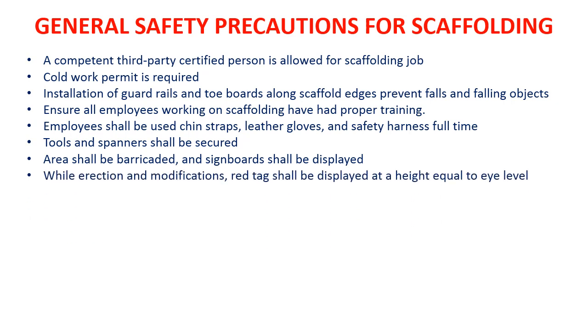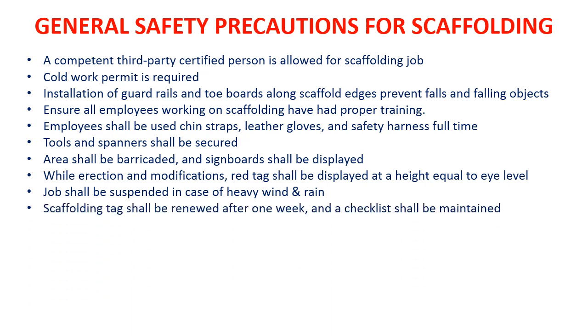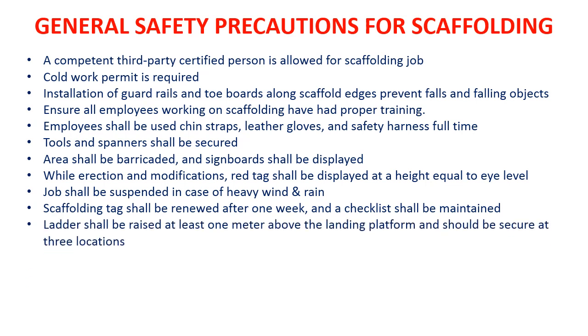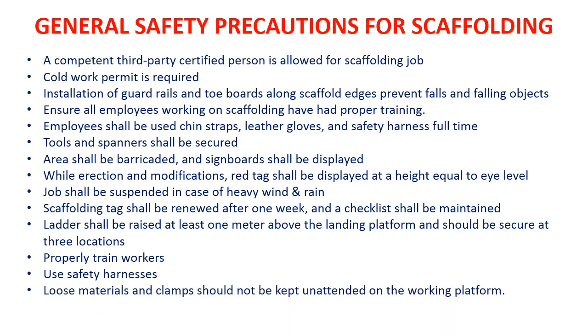While erection and modifications are in progress, red tags shall be displayed at a height equal to eye level. The job shall be suspended in case of heavy winds and rains. Scaffolding tags shall be renewed after 1 week and a checklist shall be maintained. Ladders shall be raised at least 1 meter above the landing platform and should be secured at 3 locations. Properly trained workers use safety harnesses. Loose materials and clamps should not be kept unattended on the working